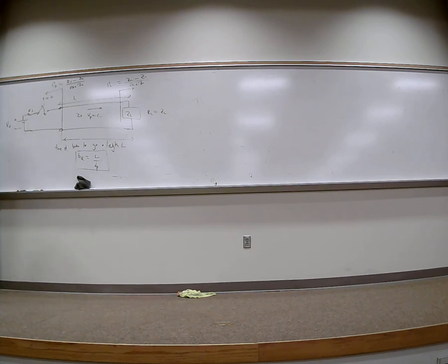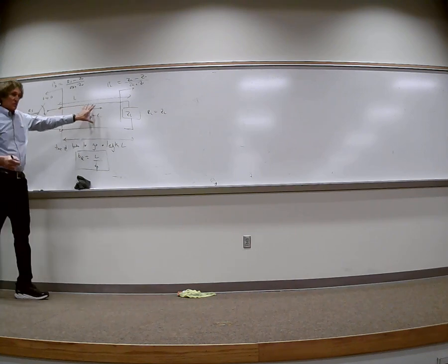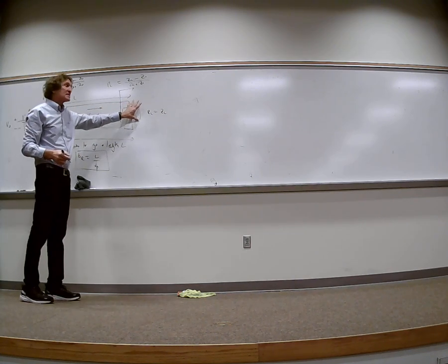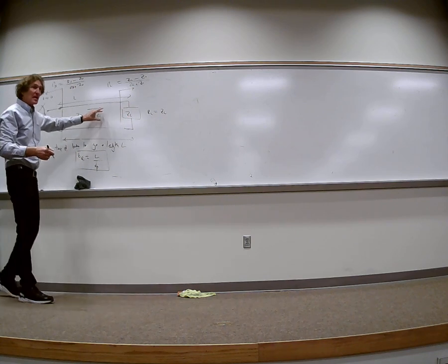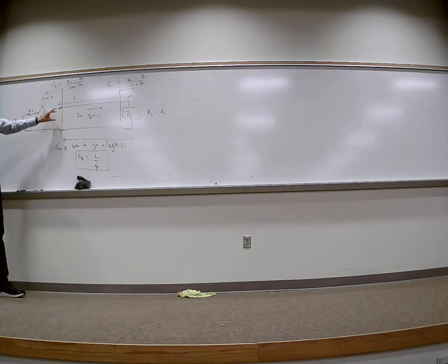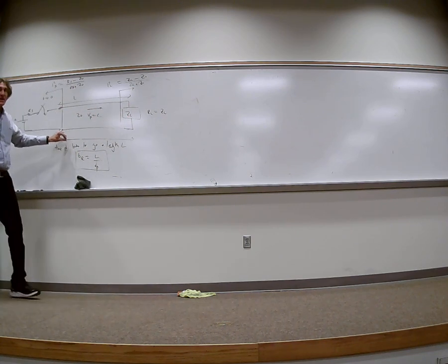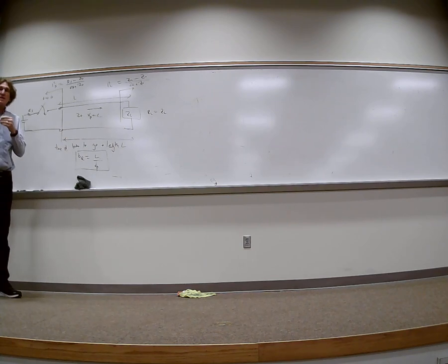So what happens? Switch closes, a certain amount of voltage, by no means all the voltage, but some of it gets on here, goes down at the speed of light, hits here, then some of it is reflected, less than actually hit there, hits here, and it keeps going back and forth, and asymptotically it goes to a steady state value. You all hear me on that?